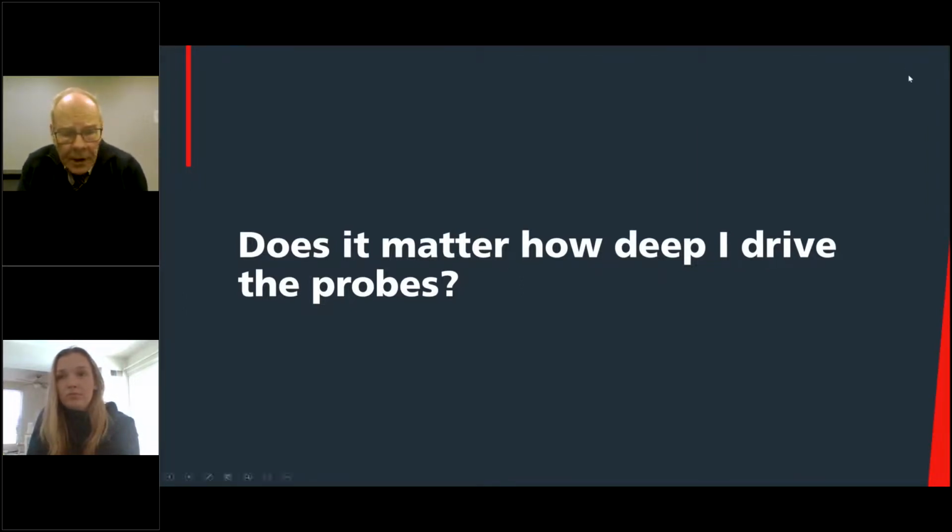Okay, again, another common question that more or less goes back to the old testers, where the operator had to make a judgment because they didn't necessarily tell you that your probe wasn't deep enough, and so they used to bang in pretty deep probes. And there's still a lot of that being done, so keep that in mind. But with the modern testers, they just tell you there's too much resistance on your current probe. Okay, you go out there and you water it or whatever.